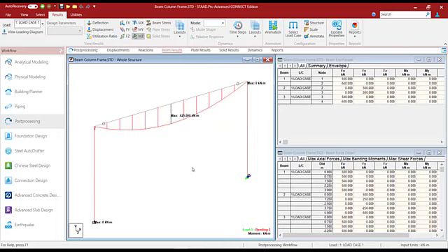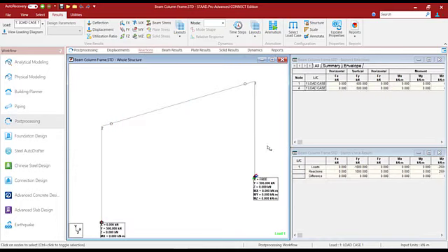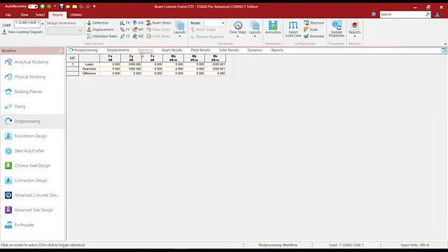And one more thing, if we go into the reactions tab and look into the overall Fy moment here, we see that the total load is 1000 kilonewtons instead of 780 kilonewtons, which we had estimated from the realistic field conditions. Obviously, our modeling would need modification to achieve a more realistic simulation of the actual problem. But what is actually happening with this particular simulation that makes the results deviate so much from the realistic results? Let us find out.